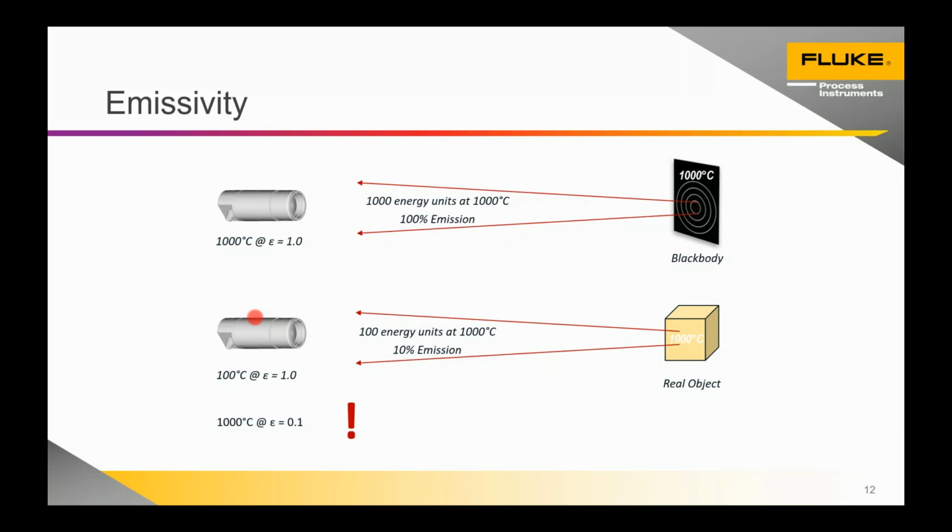But generally, annual is what we recommend, and if after 1 or 2 years you see that as returned is the same as found with no action, a lot of people extend that to 2 years, because then they're satisfied that the environment the sensor sits in doesn't have any influence on calibration. It's nearly always optical contamination. So yes, we recommend it, but it's not a must-have. It often depends on your quality manual, essentially.